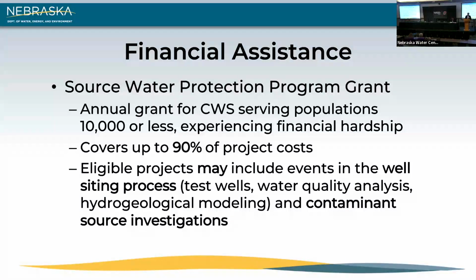Some popular projects that we've been getting requests for are those things, as I just mentioned, that are key events in that well siting process, such as drilling test holes and test wells, as well as conducting aquifer pumping tests to establish the capacity of their future well or to conduct an aquifer quality analysis. We also receive a lot of requests to remove contaminant sources, such as the decommissioning of abandoned water wells. Last year, we funded a project with the intent of decommissioning up to 25 private wells within or near their wellhead protection area, as well as 2 of their municipal wells that were taken offline due to high selenium.